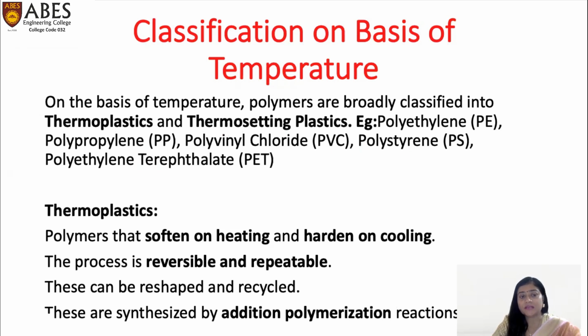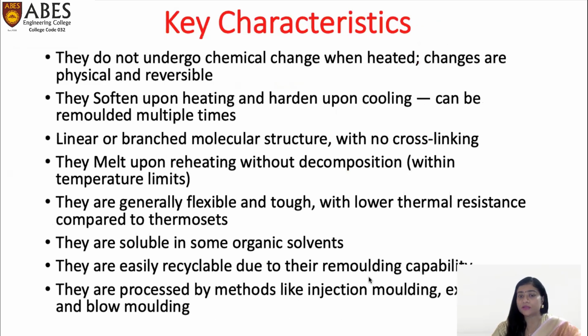So what are thermoplastics? They are the polymers that soften on heating and harden on cooling. They can be reversed and repeated, they can be recycled, and they can be melted and remolded again in the desired shape. They can be reshaped, recycled, and they are synthesized by addition polymerization reactions.